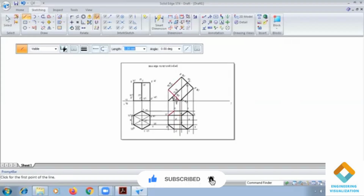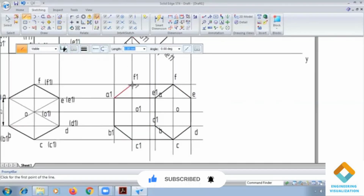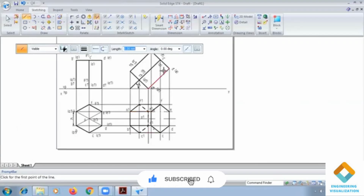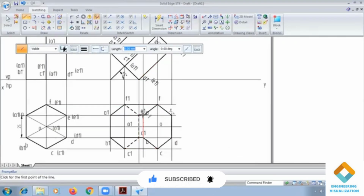This hexagonal base is not visible from the top view, so it is written with a dashed line. Here, this slanted rectangular area is also not visible. You can show part of the line here. From here to here.